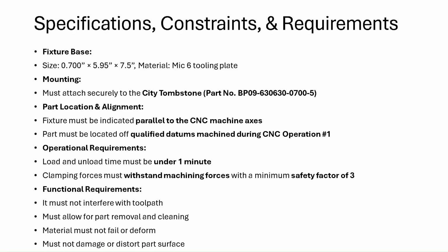The operation requirements: load and unload time must be under 1 minute. Clamping forces must withstand machining forces with a minimum safety factor of 3. The functional requirements: it must not interfere with toolpath, must allow for part removal and cleaning. Material must not fail or deform, and must not damage or distort part surfaces.